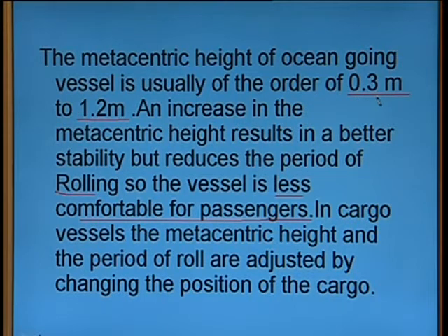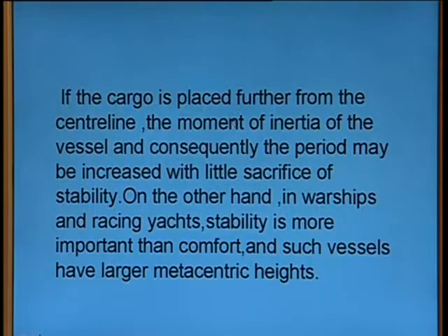So if we have a passenger ship, nowadays we have very few passenger ships, we have more cargo vessels, so we keep the metacentric height closer to 0.3. For a cargo vessel, we try to keep it near 1.2 meter to have more stability, right.